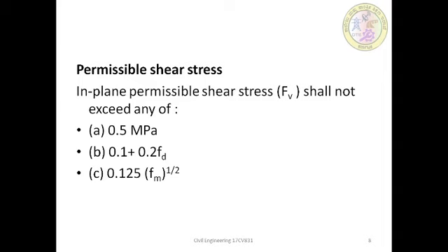Here the important thing is that no tensile stress is permitted in the masonry in case of water retaining structures, in view of water in contact with masonry. Also, no tensile stress is permitted in earthen retaining structures, in view of the possibility of presence of water on the back of such walls.